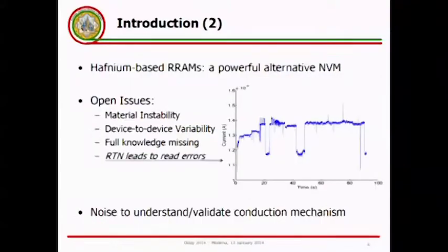But of course, there are some shortcomings or open issues. First of all, the material instability, which is to say these oxide layers are very unstable and not widely known till now. So this also causes a considerable device-to-device variability, which is an actual problem for the full industrial exploitation of the ReRAM concept itself. And moreover, a full, complete knowledge of the physics of conduction and switching of these devices is still missing. At least a unified framework is missing.